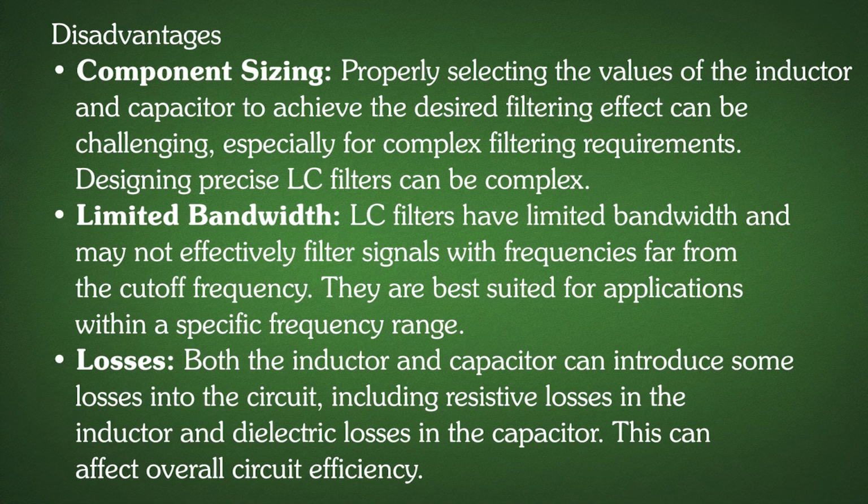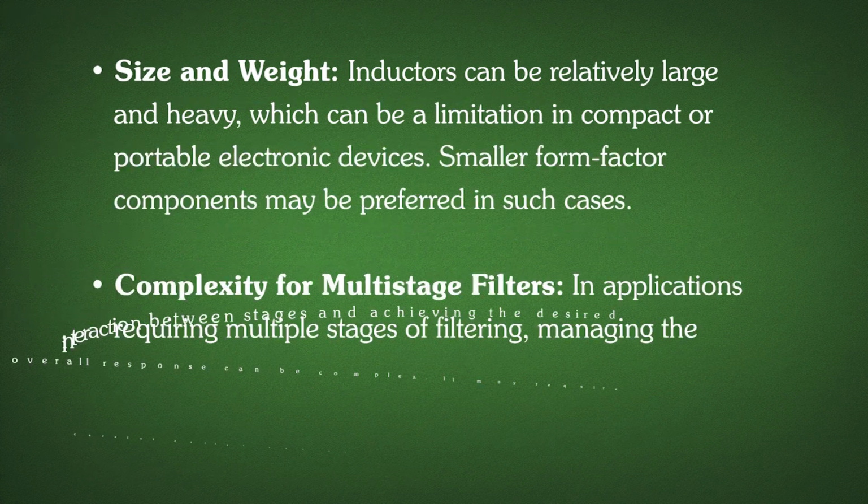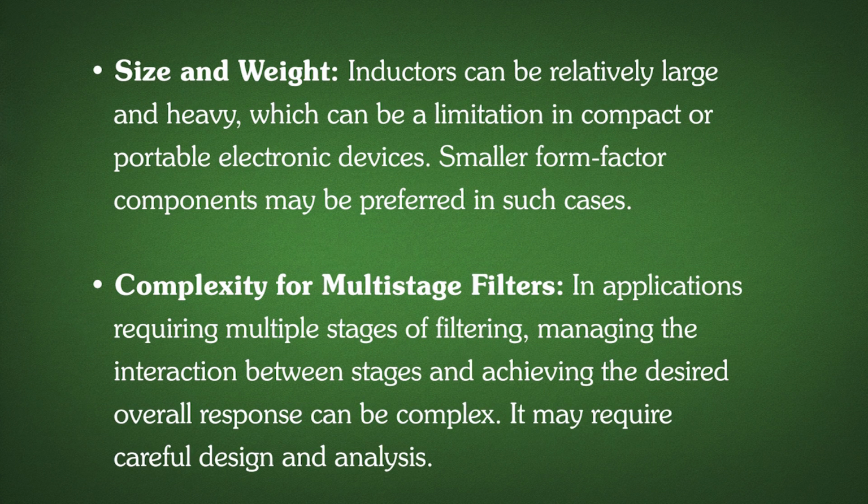Next disadvantage is losses. Both the inductor and capacitor can introduce some losses into the circuit, including resistive losses in the inductor and dielectric losses in the capacitor. So, this can affect overall circuit efficiency. Next disadvantage is the size and weight. Inductors can be relatively large and heavy, which can be a limitation in compact or portable electronic devices.